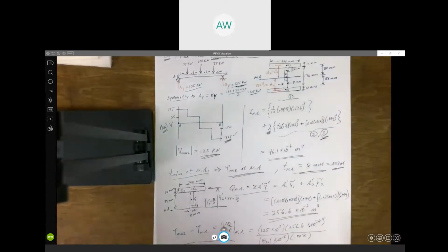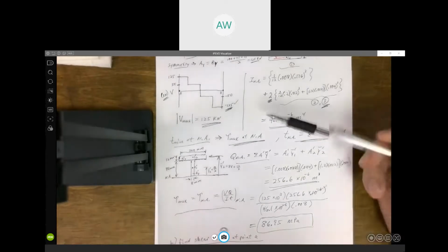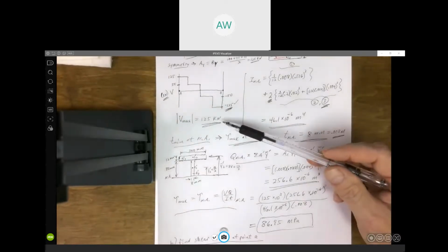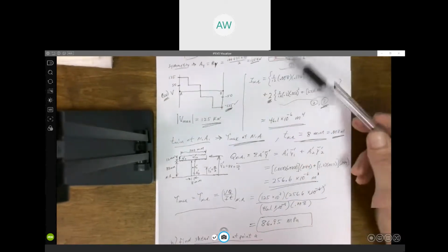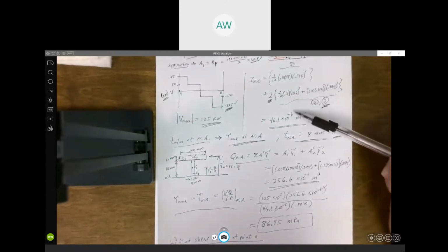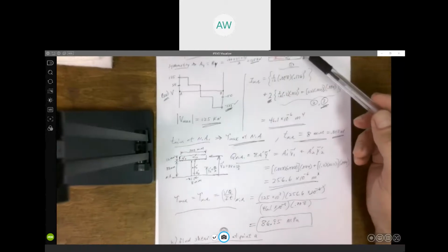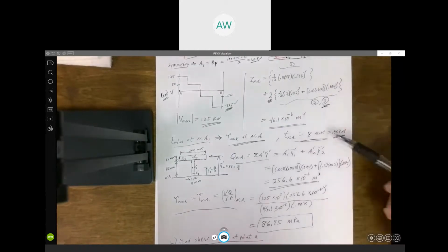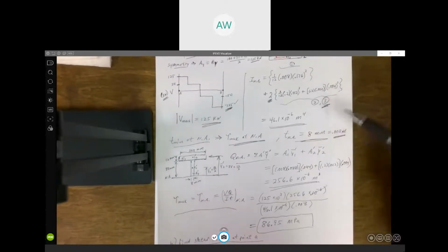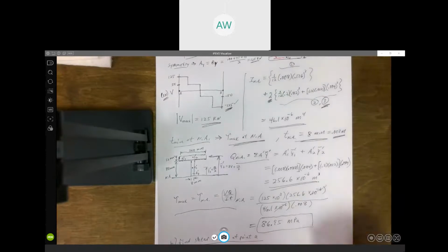All right. So the first thing to point out, V doesn't change. That's the maximum shear force on this cross section. I does not change. That's the moment of inertia for that whole cross section. It doesn't matter where you're calculating the shear stress. T could change. If the thickness at A is different than the thickness at the neutral axis, then that would be different.